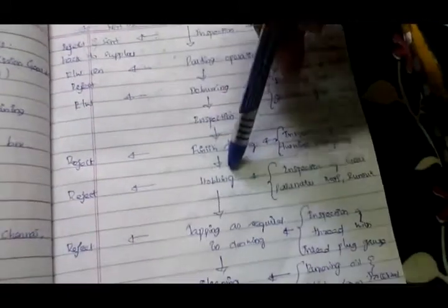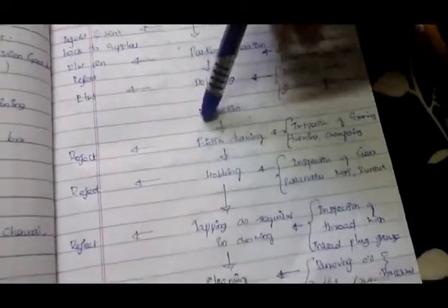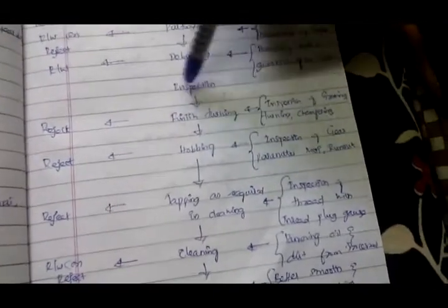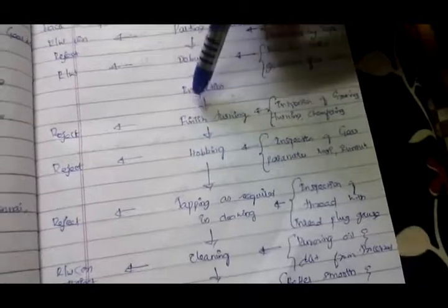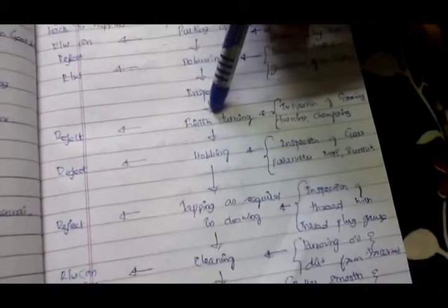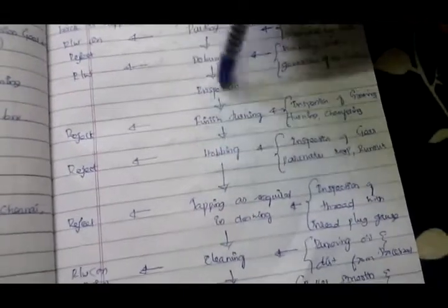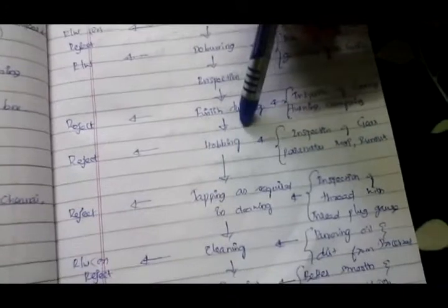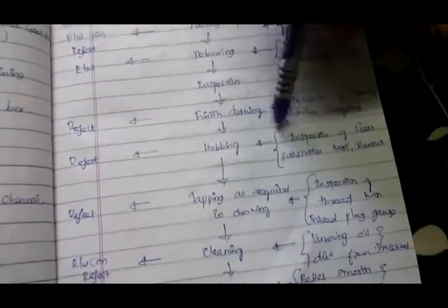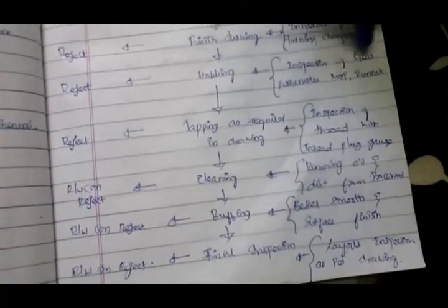In finish turning, we verify and certify all parameters, including chamfer, groove, outer diameter and inner diameter, whatever the drawing requires. And then we move to hobbing. This is the hobbing as per our requirement, where we verify the parameters, that is MOP as well as runout.